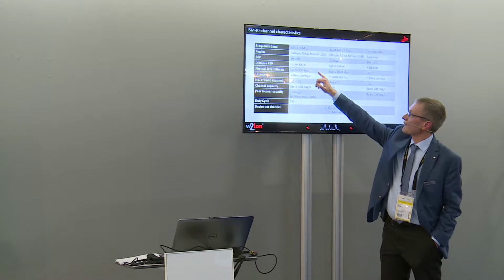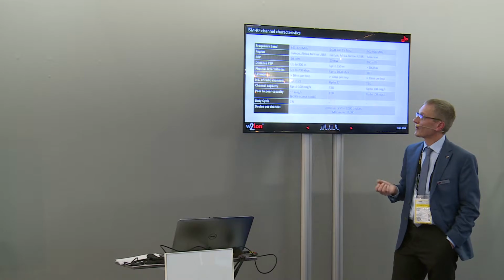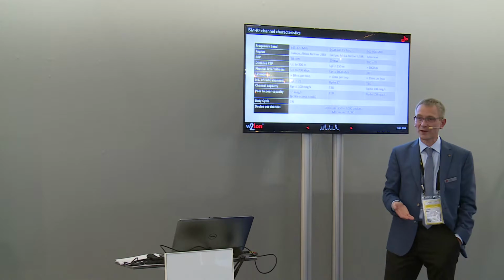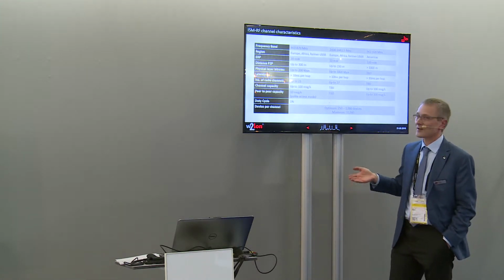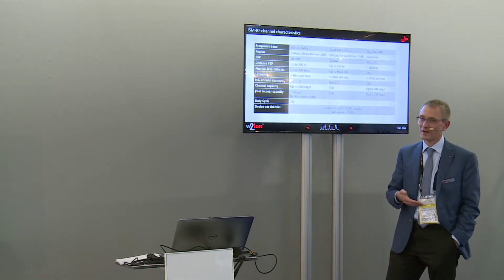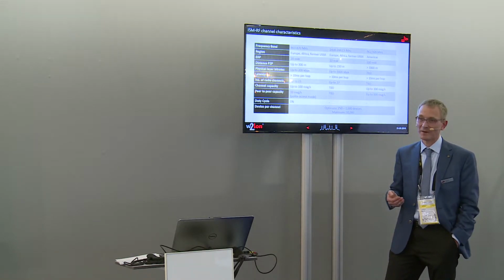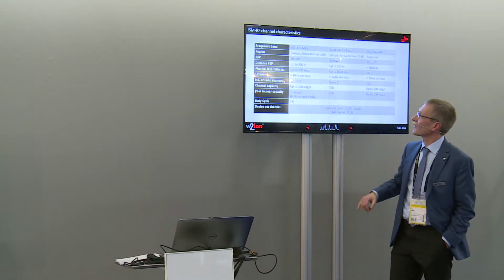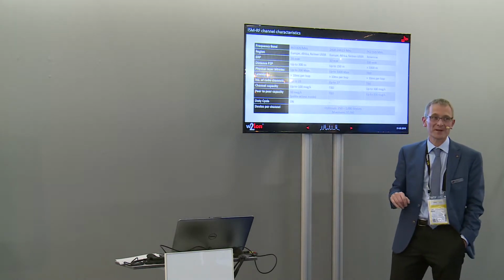But that gives us a peer-to-peer distance between the controllers, between the different nodes, of about 300 meters in air. So if you're in a building or if you have some other interference, that will be less than that. But this is the fastest as you can get. And of course, with the mesh technology, you're able to connect to devices that may be a couple of kilometers away. Then, of course, you need to have a couple of hops, and I think 255 hops are supported.